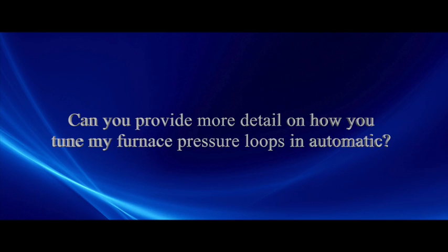So it could be hydrocarbon. It could be situations where you don't get much attenuation, and certainly pulp and paper. They're very sensitive to any sort of oscillation, and that's what Lambda tuning was originally developed for. It was developed for pulp and paper, and they thought, we don't want any oscillation at all. Since then, they've understood differently.